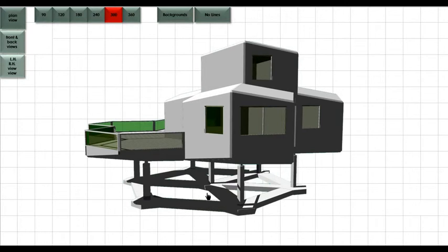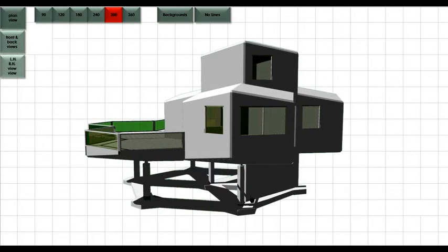Now, in this case, the columns take the swing. The house stays pretty inert. It's a large mass. It's very high. And the steel or concrete column calculated to take the horizontal shear loads and deflects. So what we do to create some friction to allow this to not sway and get into a bouncy motion, we create what I call friction walls. These are low-cost walls that we build downstairs that can serve other purposes, like a small shed, storage, or even a garage in some cases.